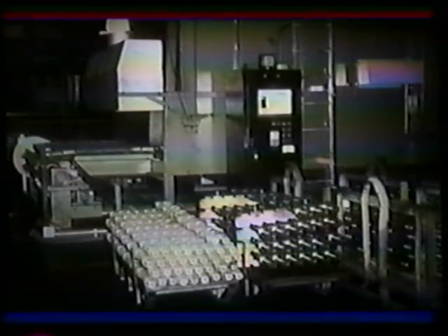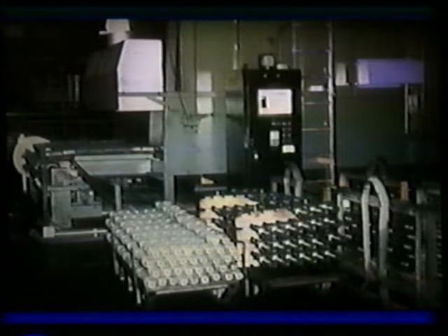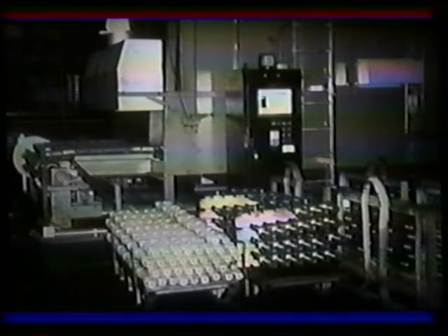The next step in the production of Caterpillar camshafts is the heat treat. This is a critical step, providing for strength and wear life. Some Caterpillar camshafts are hardened through furnace hardening and others through induction hardening. Then the camshafts are tempered to remove residual stresses. As tempering removes the stresses, it increases the toughness or the ability of the camshaft to withstand shock loads.